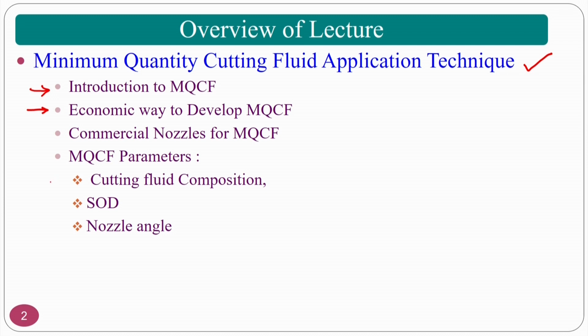For cutting fluid composition, here we will see the thermal conductivity experiment. Again we will go through just a glimpse. At the same time we will also look at the standoff distance, how far we have to keep it, and the nozzle angle, at what angle we have to set the nozzle. So these are all about minimum quantity cutting fluid.